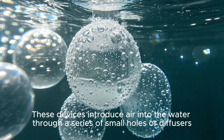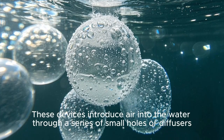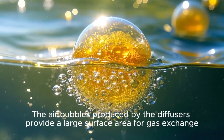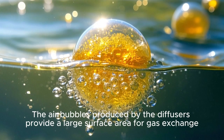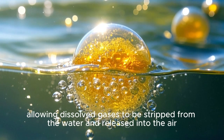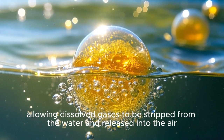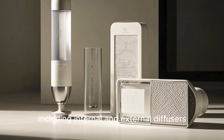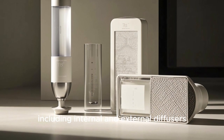These devices introduce air into the water through a series of small holes or diffusers. The air bubbles produced by the diffusers provide a large surface area for gas exchange, allowing dissolved gases to be stripped from the water and released into the air. There are several types of diffusers available, including internal and external diffusers.